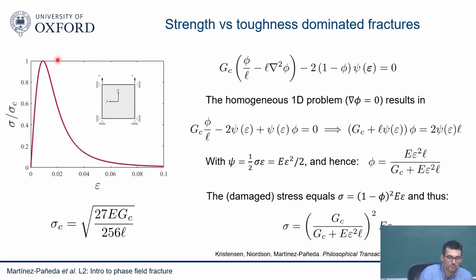So those of you familiar with cohesive zone models or some of these damage models will also recall seeing something like this. It's kind of a traction separation law. So your stress increases almost linearly. Here you start seeing some nonlinear phenomena. Eventually you reach a strength, and then you get some sort of softening degradation until you get a complete failure. This is the idea. So it's kind of a traction separation law in a cohesive zone model.